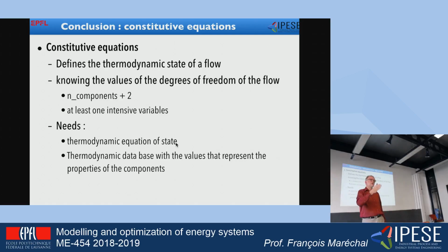You can choose this and even change from one equation to another according to what you want to calculate, because sometimes some equations of state are more precise for the equilibrium than for the enthalpy calculation, for example. You will have to choose the mathematical formula and the database that you are going to use.